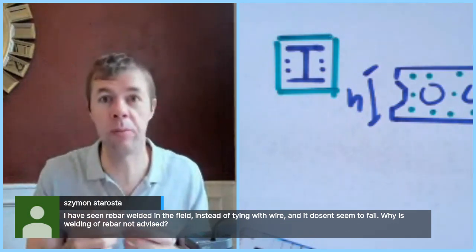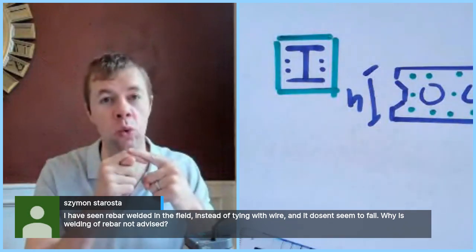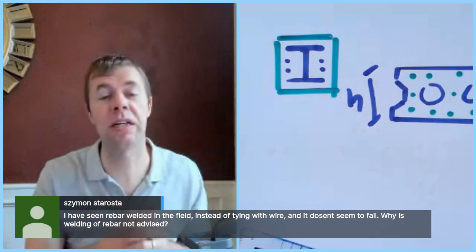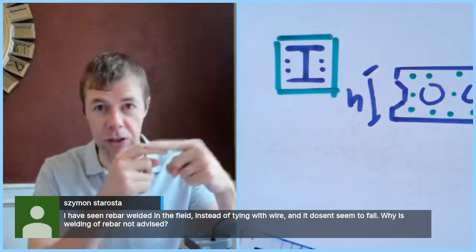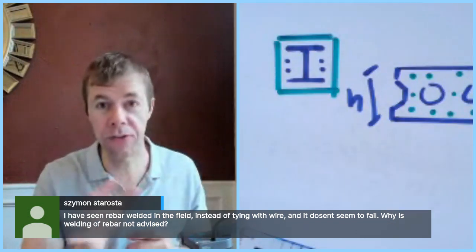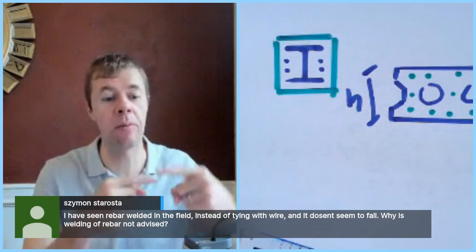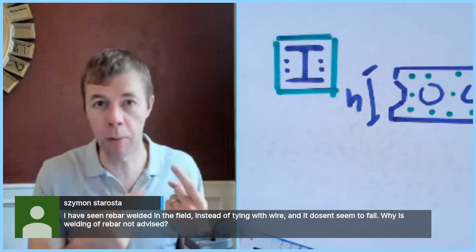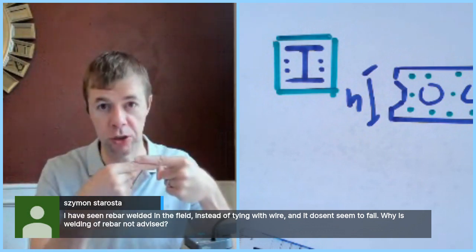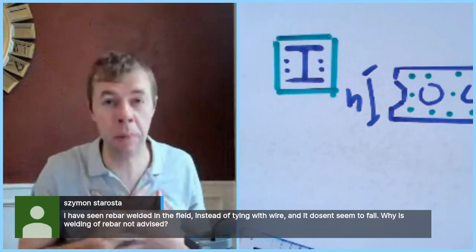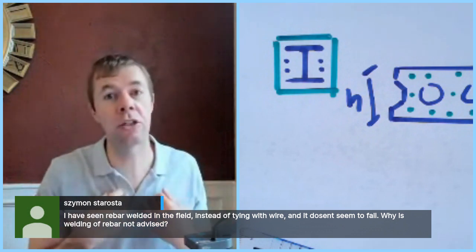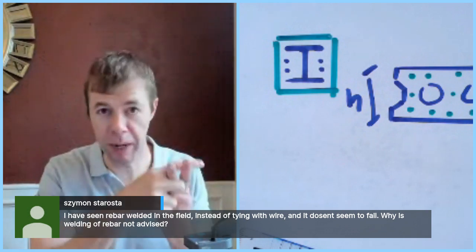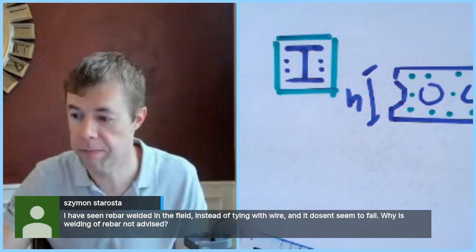Now, when I say welded rebar, I'm talking about a weld that you are needing to take load for the safety of the structure. Now, I've seen welds done in the field just to tack or just kind of hold rebar together. That's not the same thing that I'm talking about. I'm talking about a weld that is required to transfer the load. So in my development length videos, I never talked about welding rebar to transfer load because it's just rarely done in my country. Maybe it's done in yours, but in my country, you have to have a very, very specialized welder and a very, very specialized inspector to make sure that those are done correctly.